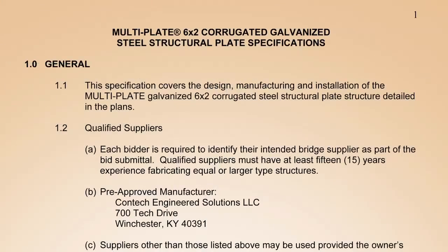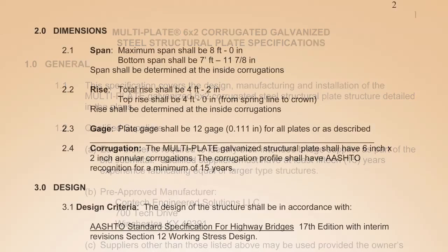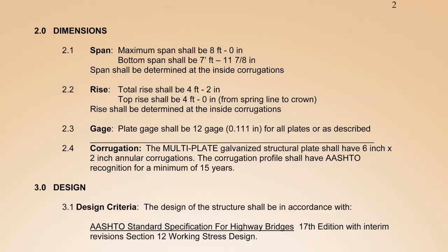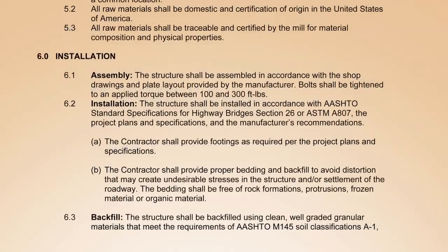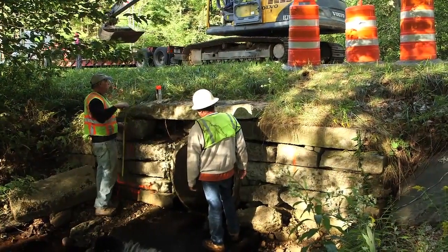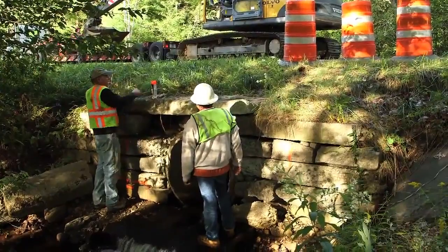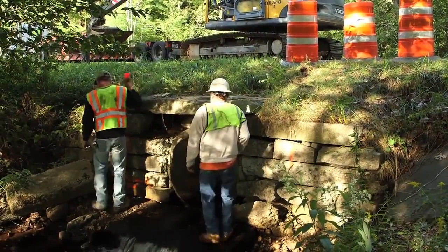Other sheets of the design, specifications, and construction notes include specific details for the assembly of the culvert and associated components, and should also include the specific requirements for water, erosion, and sediment control. The construction drawings should be provided to and reviewed with the contractor prior to construction.